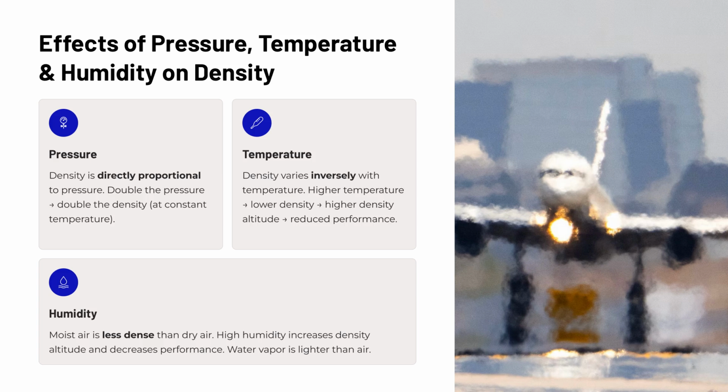Temperature works in the opposite direction. Density and temperature have an inverse relationship. As temperature increases, air expands and becomes less dense. Lower density means higher density altitude, and higher density altitude means reduced engine power, reduced lift, and longer takeoff distances.